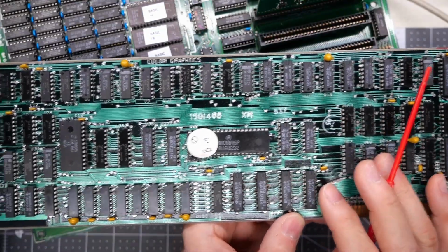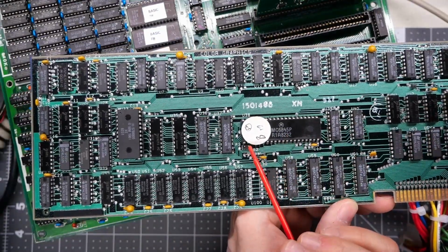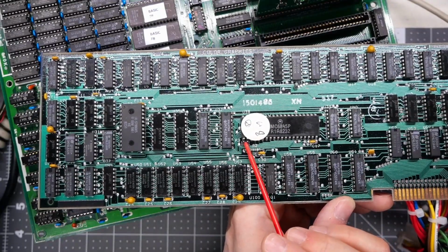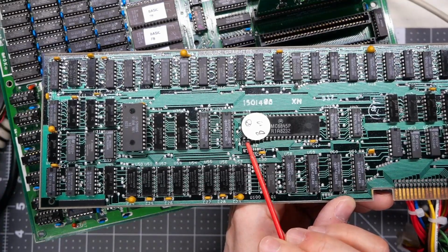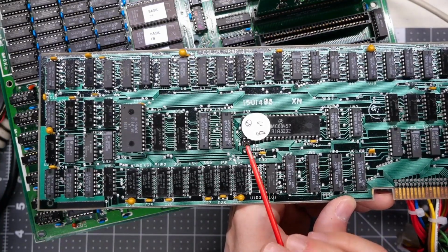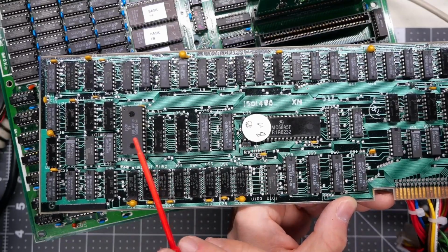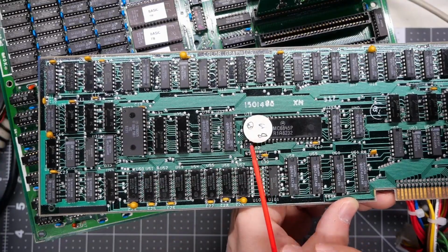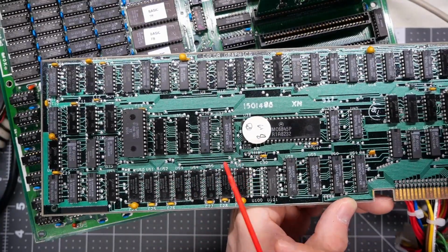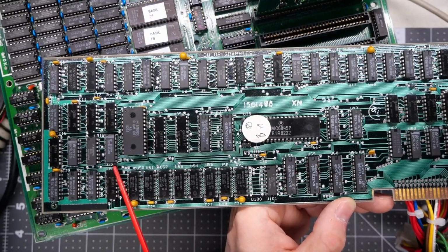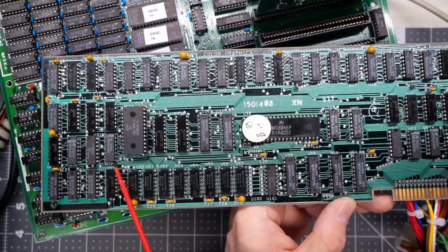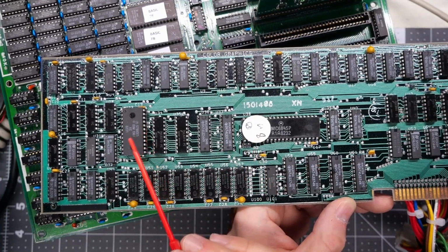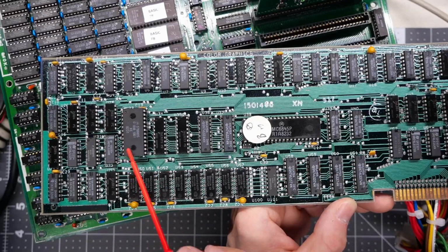I also went and installed a couple other mods which I haven't really talked about yet, but I put a 2-pin block right there. This is P3, which is actually a jumper that I don't know if this is even installed on any of the actual IBM CGA cards, but the footprint is there. And if you install a jumper on here, that has the effect of turning on the 1 character wide font. Normally you're running with a 2 character wide font. Well, putting a jumper there enables that thinner font. Now I did go ahead and install an extra pin right here as well. I didn't cut any other traces, but I just installed that, and that is for something I want to try later. But I've never actually tried this jumper here to see if this will really work in 1 pixel wide font.